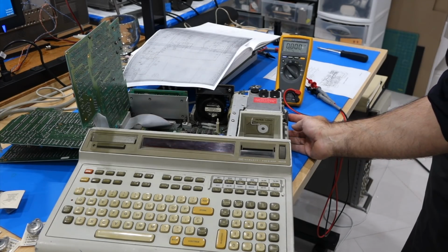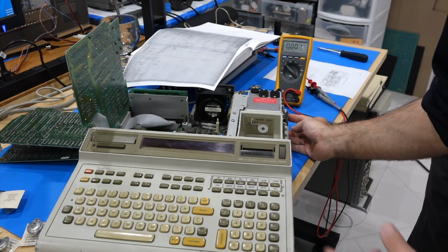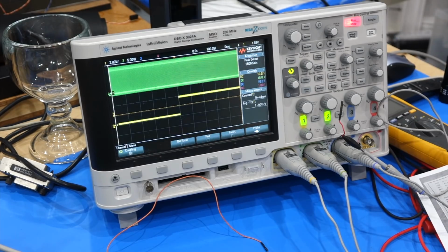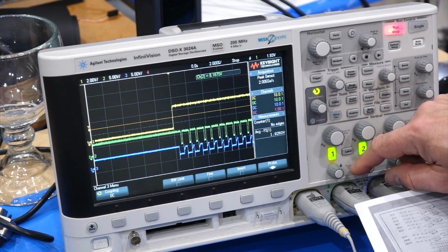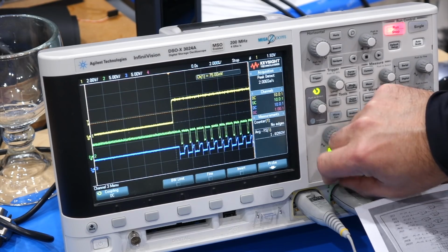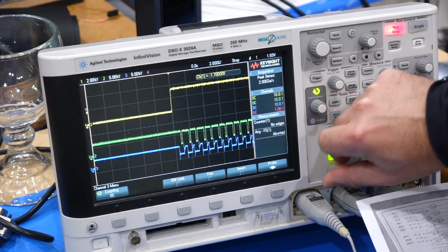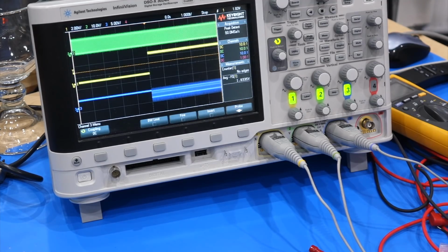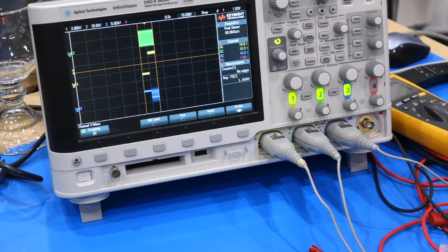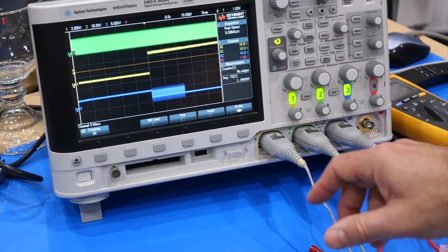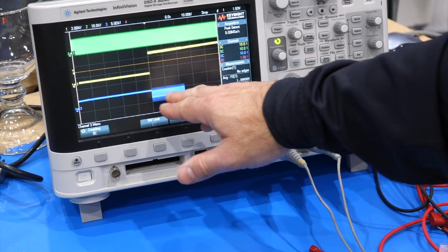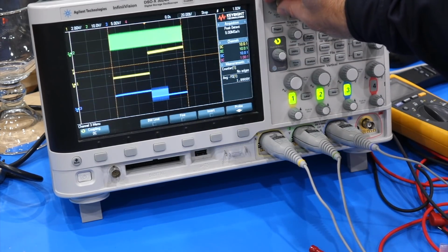We then checked for signs of processor life in the second episode. We got the 2 clock phases, the reset signal, control signals for start and end of memory cycle. So the processor was not completely dead and was at least attempting to read memory. But we can already tell that something is very wrong, as the processor gives up reading memory after about 15 milliseconds of trying. Time to call in the HP Logic Analyzer for the rescue to see if we can get some clues about what is happening.